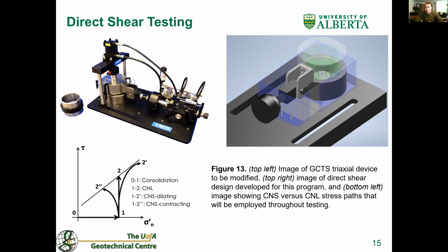The existing servo-controlled apparatus that we have can be programmed based on vertical or horizontal force and displacement. This also allows us to be able to complete unload and reload cycles on our samples. These unload-reload cycles are of interest because the accepted industry practice at this time is that the stiffness of a shear plane is assumed to be constant throughout the shearing process. The programmability of our device affords us the opportunity to better quantify if there's a change in strength or if there's a change in stiffness of the material throughout the shearing process.